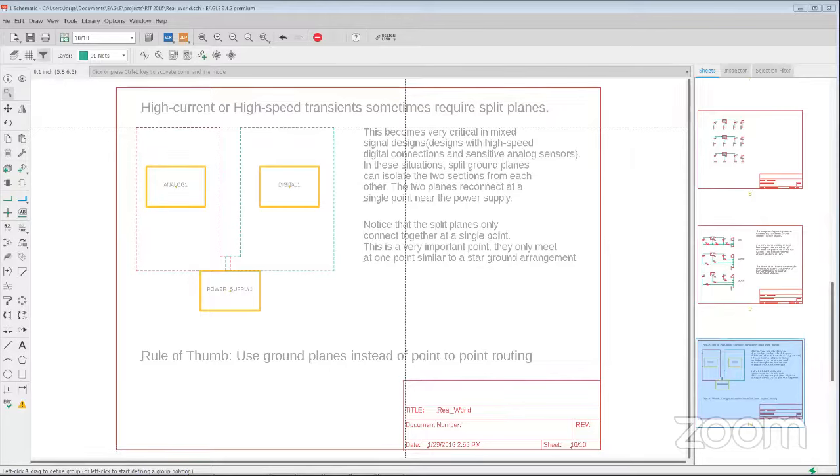It's whatever convention, as long as you're consistent, then you'll be okay, because Eagle will define each supply symbol as its own net. So you have to be careful that you don't have, for example, two different supply symbols in your library called DGND. Because they have the same device name, even though they look different, they're both going to be connected. So that's the only thing to be careful with. But by default, in supply 1 and supply 2, we don't have that situation going on.